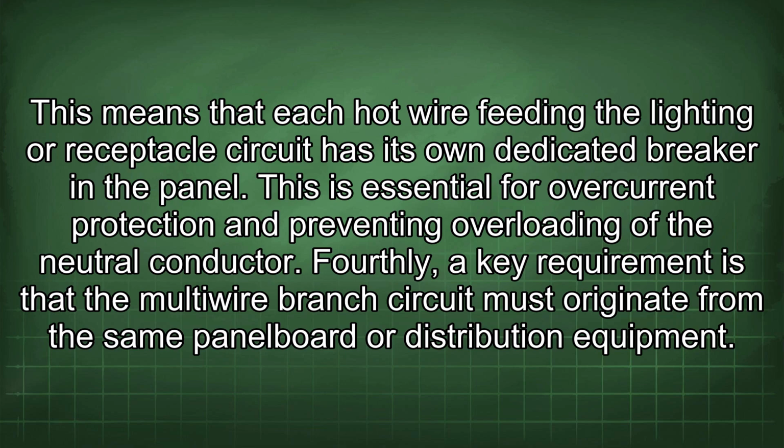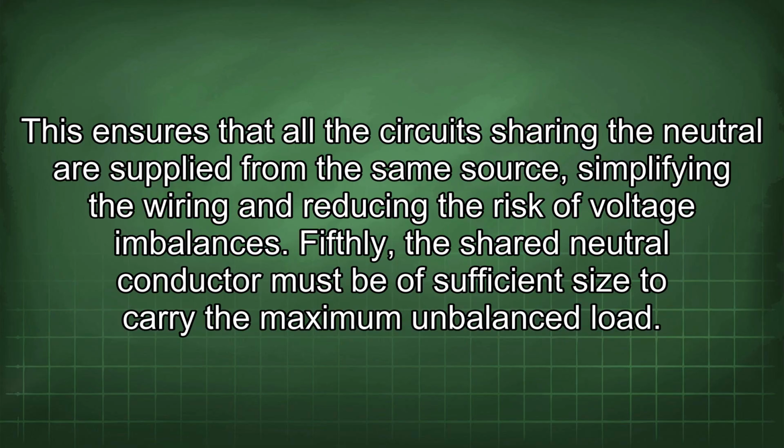Fourthly, a key requirement is that the multi-wire branch circuit must originate from the same panel board or distribution equipment. This ensures that all the circuits sharing the neutral are supplied from the same source, simplifying the wiring and reducing the risk of voltage imbalances.